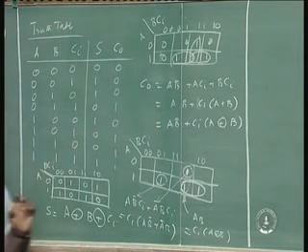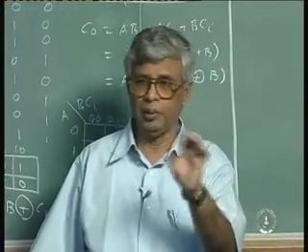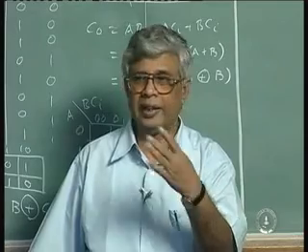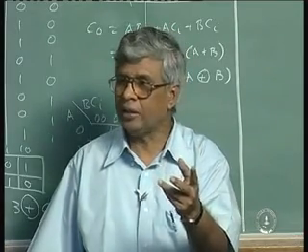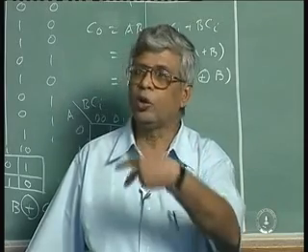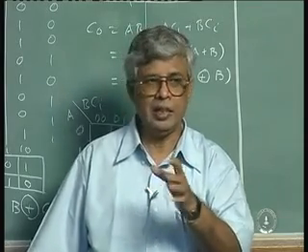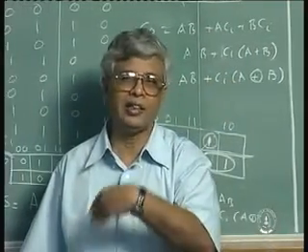Now what we have done so far is to do a half adder, 2 bits, both A and B, to be added. 2 inputs, 2 outputs, a half adder. Not of much practical use except in the least significant bit where there is no carry input. But generally when you are doing a multi-bit addition, 1 bit not having a carry is not significant at all.